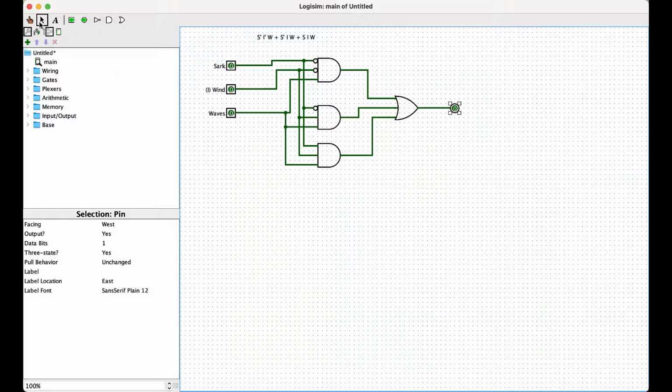So remember, there aren't any waves. Remember, I said it's really good. I want to go surfing when there's waves. I turn that on. You see that voltage turns high. We can see that that actually activated this AND gate, turned on that circuit, and went high there. So remember, an AND gate, if all the inputs are high voltages, then its output will be a high voltage as well. So it goes through the NOT gate, we can't see it, then it becomes a high voltage, this too, and so we have 3 high voltages, and that turns on the AND gate. Okay, so remember I said I'd go surfing if there were wind and waves, and sure enough, that turns on.